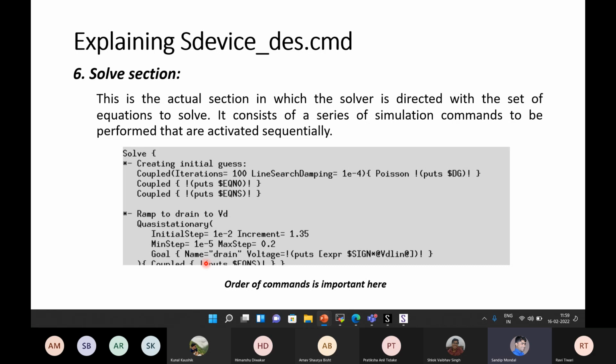So for example, you remember that when we are doing the CV measurements, we first fix the DC voltage at a particular step. Then we apply the AC and measure the capacitance at that point. Then we go to the next step, increase the DC voltage, and again we apply the AC. Then we find the capacitance at that particular DC voltage.